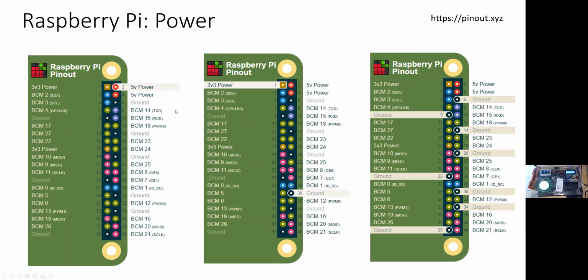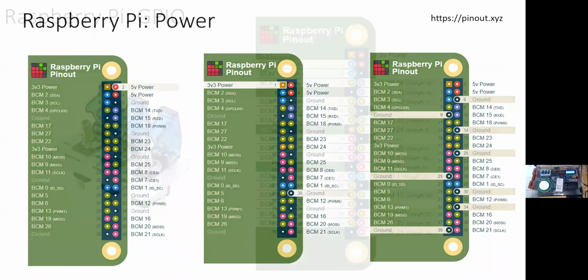So I really had to think about power, because switches and LEDs don't need much power at all. But once you get to those lights, especially the LEDs, one of them doesn't draw much, but there are 40-odd altogether, and they start to draw a lot of power. So you can't power those from the Pi.